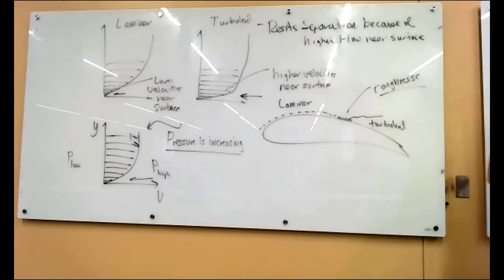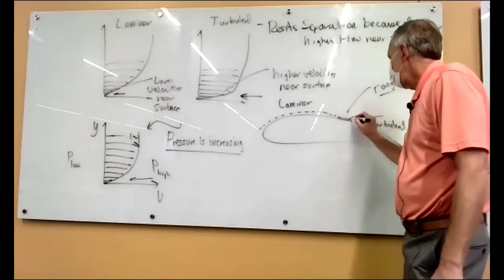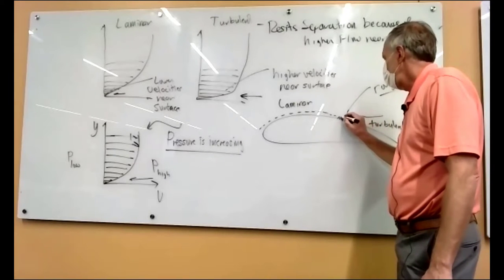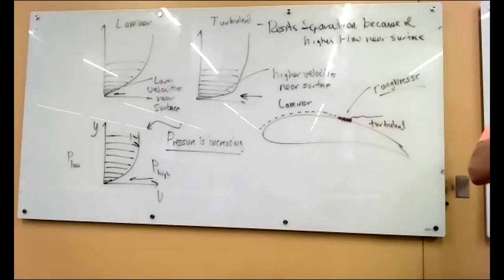When people build wind tunnel models to test their airplanes, the wind tunnel models are smaller. So that Reynolds number, remember it's Re and it's the dimension L or X. So the smaller scale models don't behave the same as a longer plate. And so what they'll deliberately do on the model is they'll put a roughness here, a trip strip, to trip the boundary layer at the point where it actually trips on the full-size airplane. So they test the correct boundary layer in the wind tunnel for their little model.